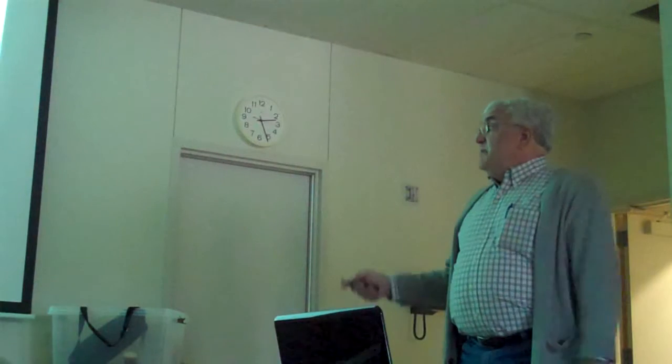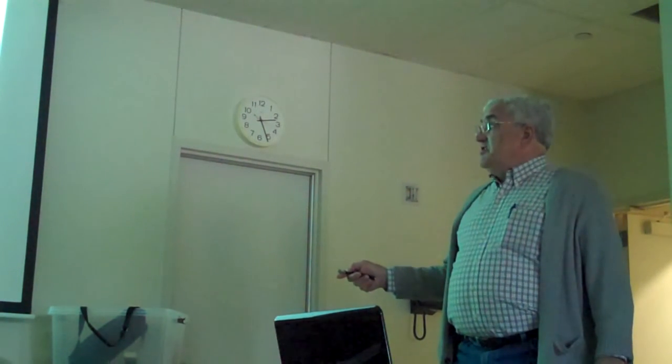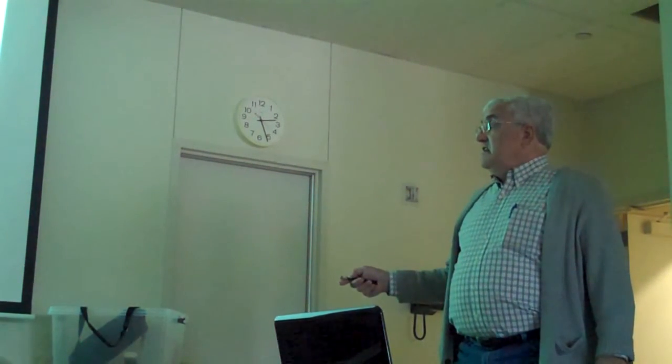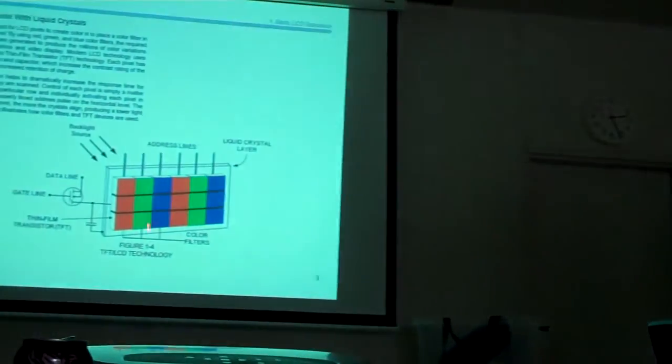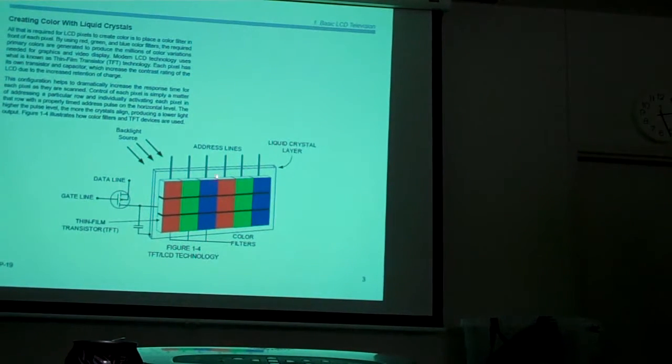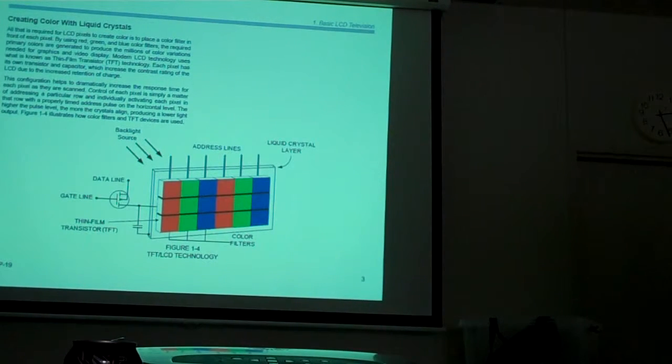But, so to your question, which is very good, in this case, if we wanted to make this panel white, we would make the red 59% of the light, the green 30% of the light, and the blue 11%. And for some forms of high definition, that ratio is slightly altered, but not by more than about a percent or two. So it's very close.